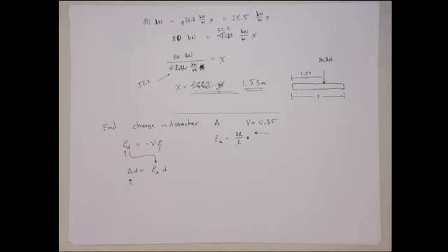I should stop here. There's actually two ways you can imagine doing this. You can get the strain by figuring out the reaction forces. Then knowing the reaction forces, you can get the stresses, and then using Young's modulus, you get the strain. Actually, probably that's what the book intends you to do with this problem. Since I used the elongation formula, I got delta L in the first part, and I can use delta L over L, the strain definition, to give me the strain in A. All right. So there's probably two ways to do it.